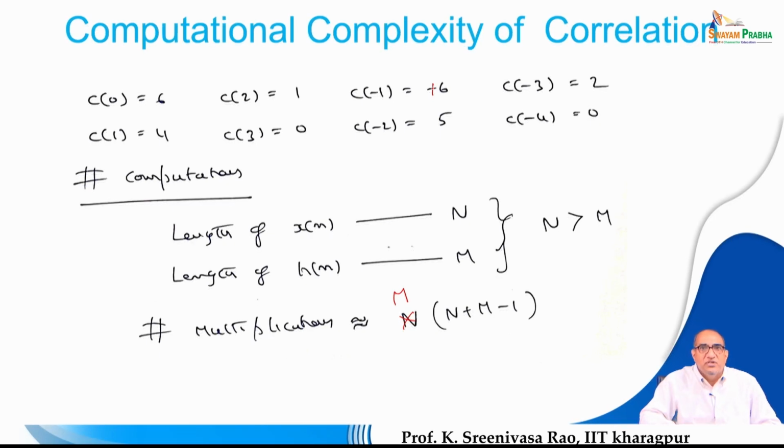The same thing I just mentioned for correlation, the same analogy or explanation, can be applicable for convolution also, because for convolution and correlation the number of multiplications and summations will be exactly the same, right. The only difference is that in convolution, as we observed graphically, we rotated one of the sequences, and then afterwards we shifted and computed the overlaps between the 2 sequences, and we estimated the product of the sample amplitudes under the overlap. That way you can compute the correlation sequence or convolution sequence.